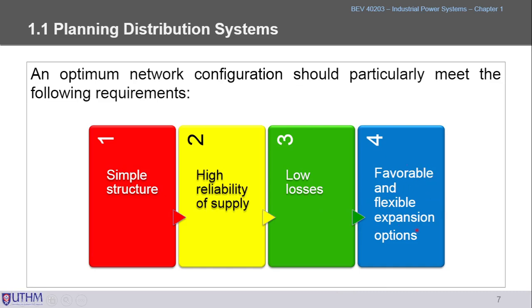And variable and flexible expansion. So of course when you design for the IPS, you need to think following the standards, the code of practice. For the IPS, we need to have some reserve or spare, as what you have learned in the utilization. So when you design the electrical network for a house, for example, we need to have at least 10%.